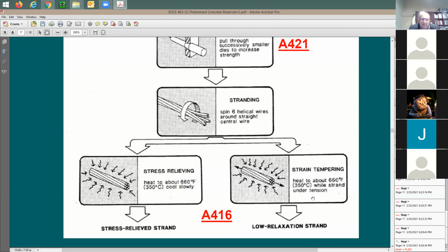This process here, as you know, the losses, if I need to go back here and talk about the losses in the strands and in the tendons, loss is going to happen because of 2 components. One of them is going to be the concrete. You're going to have strains in the concrete. You're going to have shrinkage. You're going to have creep strain, and also you're going to have this elastic strain, which means instantaneous strain. So one component is going to be the concrete. It wants to come down inside. It wants to get smaller. And for it to get smaller, you're going to have some losses because you're going to be losing the amount of tension that you put into the strands. It's going to be one component of concrete.